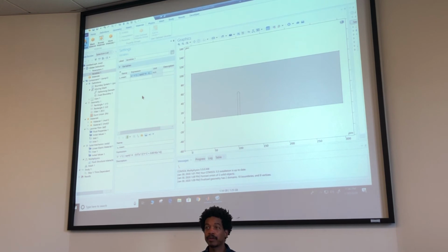The y parameter? Oh, in the last expression? Yeah, that y is actually a COMSOL variable. So COMSOL already knows what it is. Because here's what I think will happen. I think it'll turn red if I try to define it. Yeah, see? It turned red, because that's one of COMSOL's own variables. So if I would have said y1, then it would be okay with that, right? Yeah, but good observation, though.